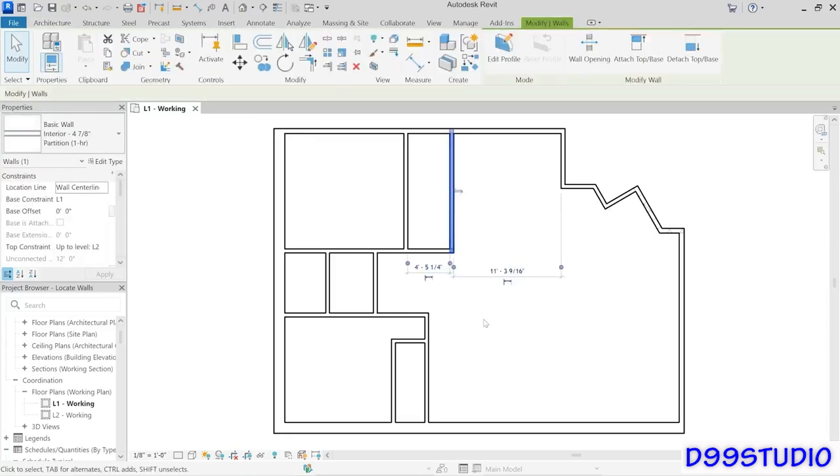I'm going to pick this wall, and what I want to do instead is click right on that numerical value instead. That will activate it as a piece of editable text, and now I will type in the value I want. Now, if you're working in the imperial file, you want 8 foot 1 inches. And again, you can either do 8 foot symbol 1 or 8 space 1. If you're working in the metric file, put in 2575, 2,575 millimeters. Notice that that will move the wall over to the right.